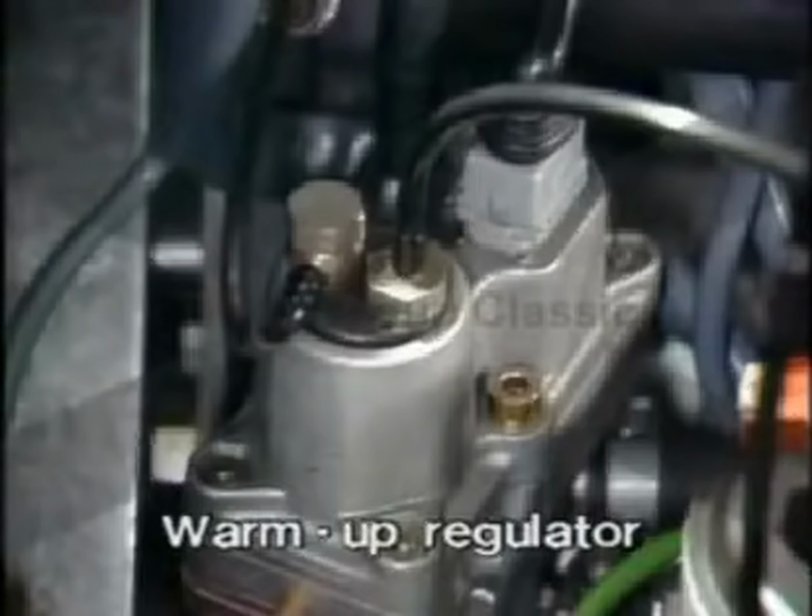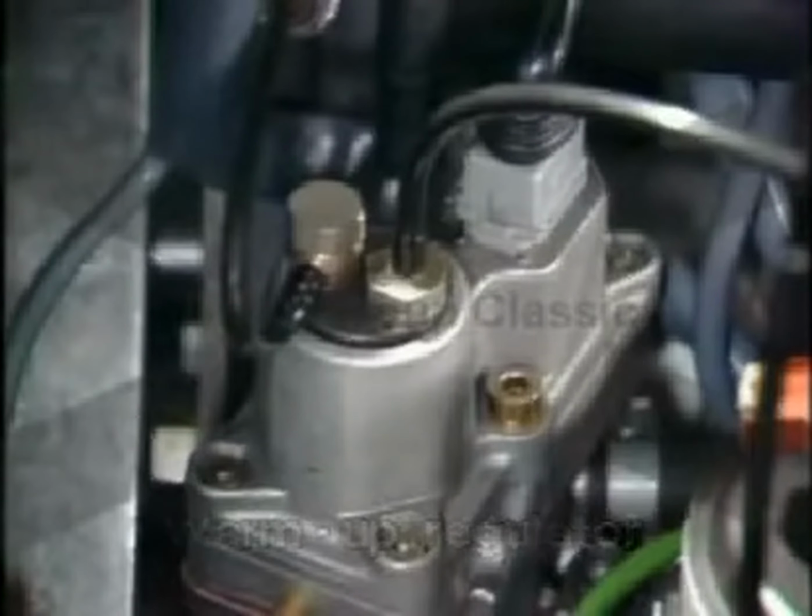The warm-up regulator. Its job is to adapt the composition of the mixture according to the engine temperature and load. How is this achieved? When the engine is cold, a bimetal strip causes a lowering of the control pressure.